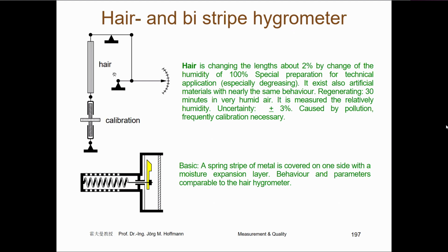In the past it was really hair from horses, but today we have artificial materials that we can use, so that with the humidity you have an extension of the hair, and you can show the humidity very roughly, but you also have problems with pollution of the hair.